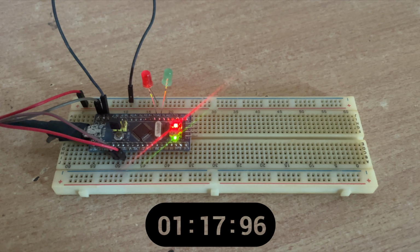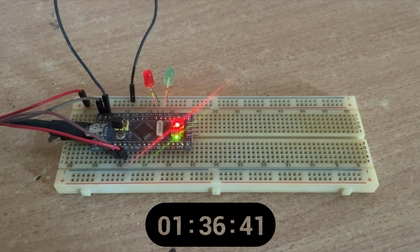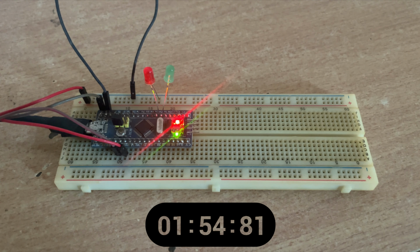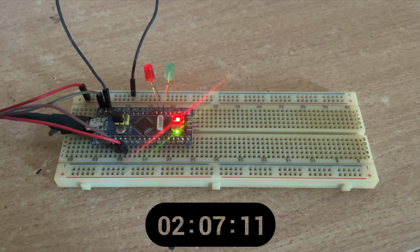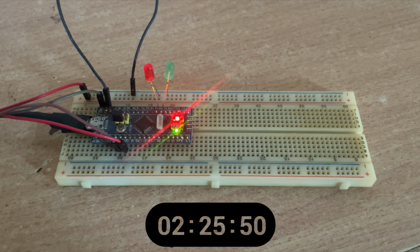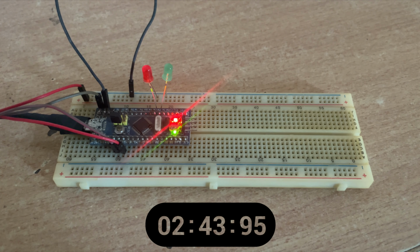To be honest, this issue cost me almost one full day to figure out. At first, I thought it was a software bug. I checked the RTC configuration, the alarm setup, the interrupt, everything looked correct. But still, the behavior was completely unpredictable. Finally, I realized the problem was not in the code, it was the hardware. The cheap crystal on this board was either inaccurate or not working properly. So if you ever face something like this, don't just debug software, always question your hardware too.